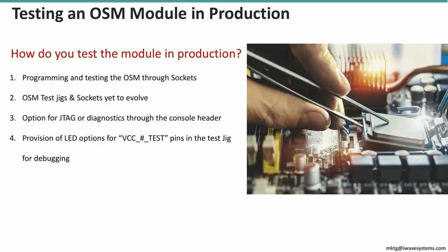And also the specification offers pins for connecting the voltage pins. So you can bring all the way up to 8 pins to the module, so that in the test jig carrier you can have LEDs. So you can check whether CPU core power or the IO power or DDR power is present. So you can just connect, and it's a very nice feature. I think it's really a well-thought-out feature from the specification committee. It's really good for debugging and also during production.